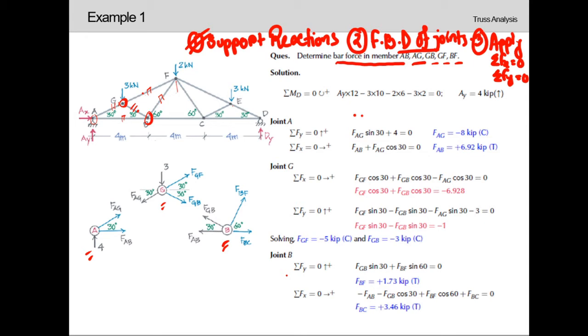So we can see at joint A, there are two member forces, which are AG and AB. As we need to denote away from the joint, denoting it with FAG, force acting in AG member, away from the joint. And similarly, force acting in AB member, away from the joint, which will be FAB. Similarly, we need to draw the free body diagram for G joint as well.